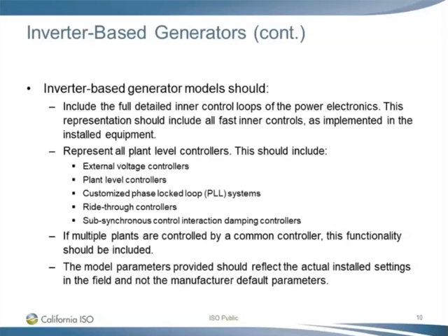PSCAD models of inverter-based generators should include the full detailed inner control loops of the power electronics. This representation should include all fast inner controls as implemented in installed equipment. All plant-level controllers should also be represented, which include external voltage controllers, plant-level controllers, customized phase-locked loop PLL systems, ride-through controllers, and sub-synchronous control interaction damping controllers.